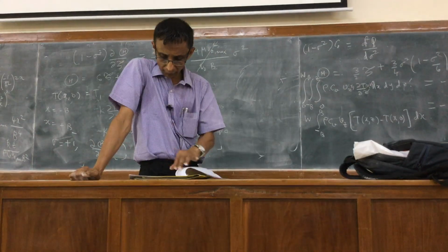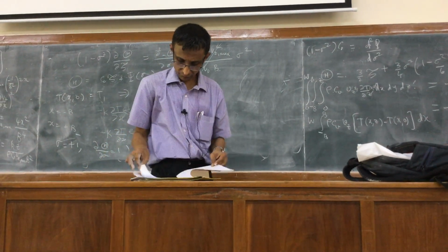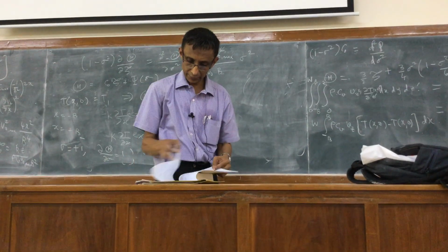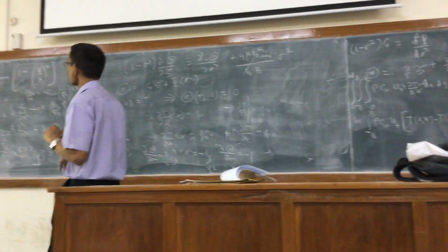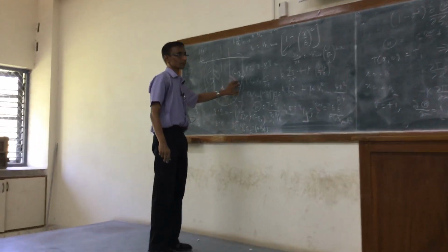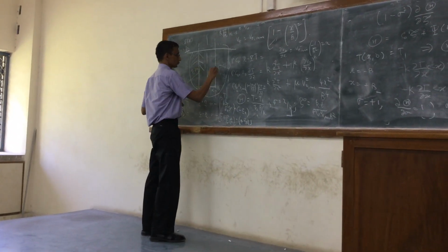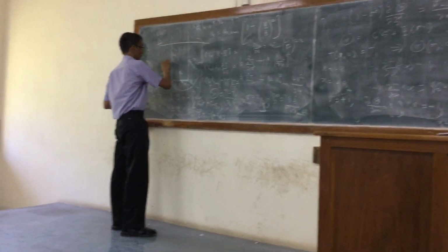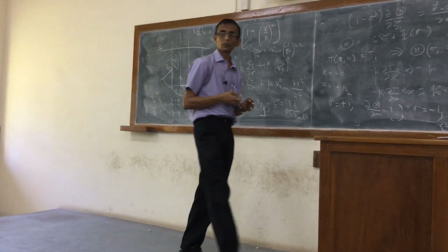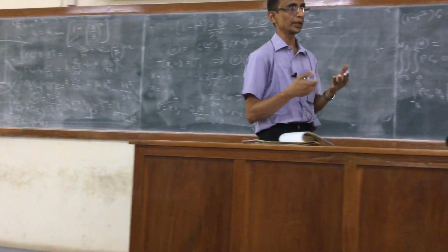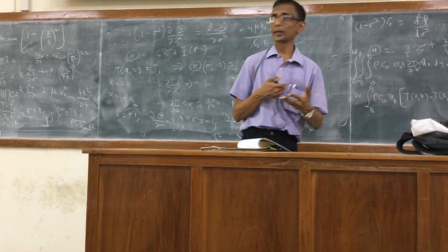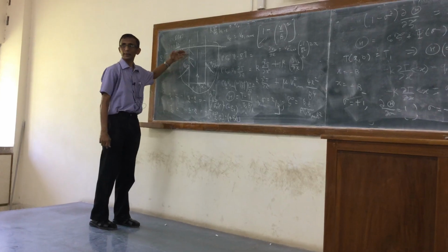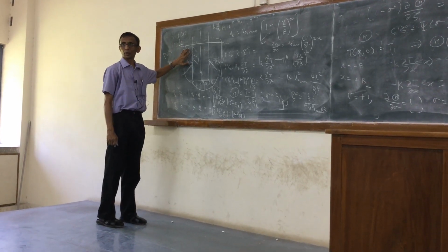Now to do the other one, minus q dot n dA, that has now to be done for the two parts separately. Probably they will add up to be the same. If both are coming to the constant heat flux q naught, that integration would now be over the area, right? Because it's constant q naught, I can easily do it, because it's constant q naught at all points.